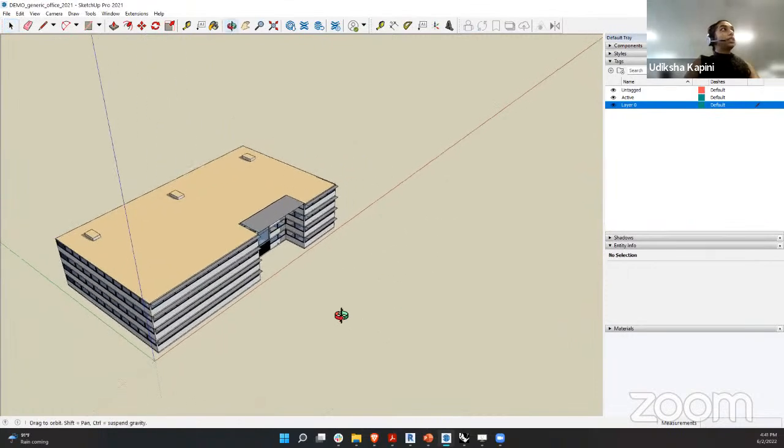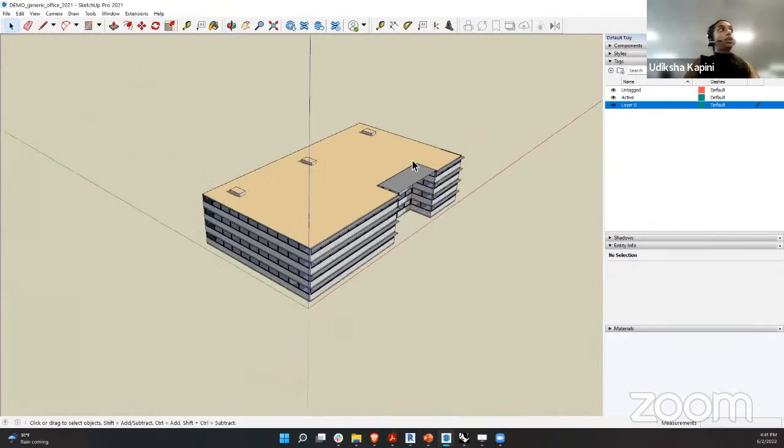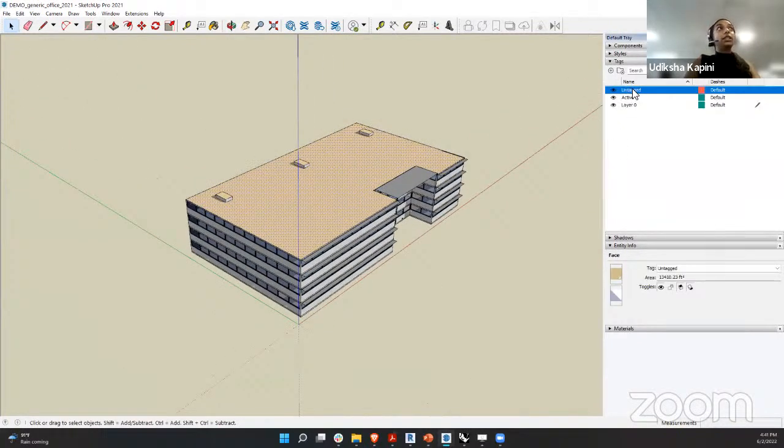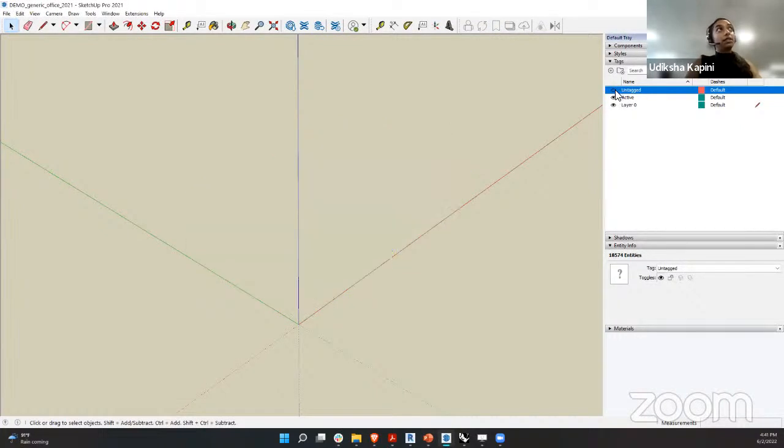Once we have that project selected, we would then go into step 3, which is to make sure everything in the model is part of the untagged layer. So the plugin looks for geometry that is exploded and single surfaces only, and all placed in the untagged layer. And again, to make sure that your geometry is present in the untagged layer, we have another button right here, which says move to untagged. So that's going to ensure that your geometry is all visible in this untagged view.